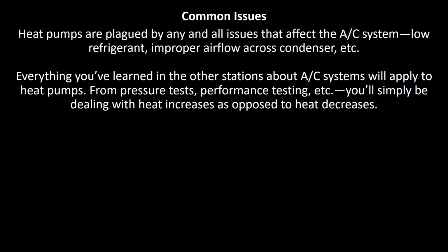What are the common issues of a heat pump? So heat pumps are plagued by any and all issues that affect the AC system: low refrigerant, improper airflow across the condenser, etc. Everything you've learned in your other stations about AC systems will apply to heat pumps, from pressure tests, performance tests, etc. You'll simply be dealing with heat increases as opposed to heat decreases.